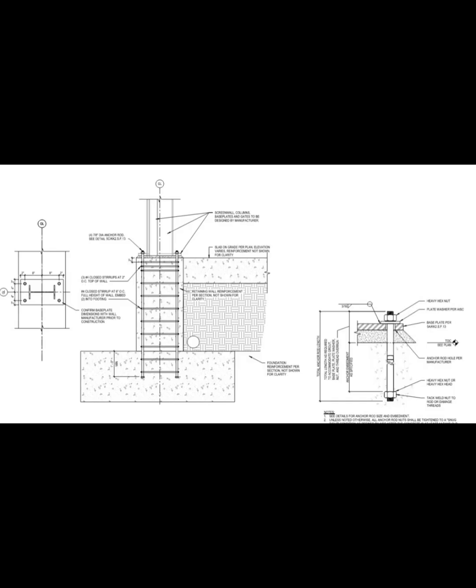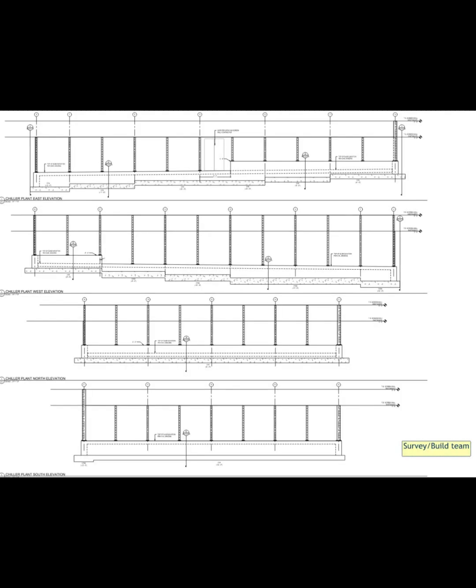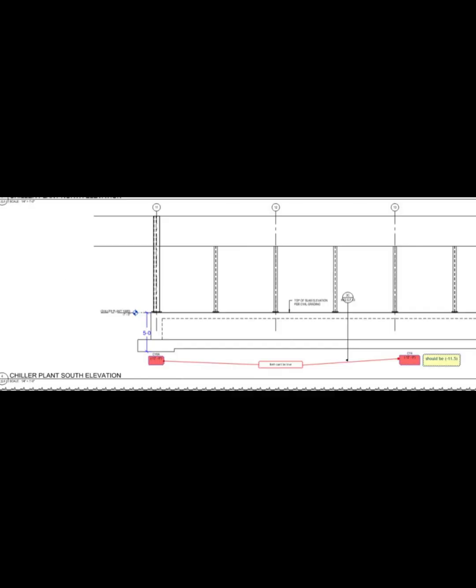More on this later. These structural elevations show how the footing step and the type of footings with depth below control line. The control elevation is at -7, and the bottom of footing at the corner of U-line and 11 is -12. Thus the bottom of footing is at 5 feet below the control elevation. This is where we start.